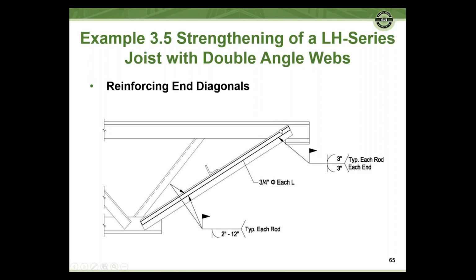Now, if you find out that you don't have 11 inches here, remember, we looked at it as 3/16. We found out this web member was a quarter. We could always increase the weld size to a quarter, or we could add weld along the inside edge at the toe of the top chord or bottom chord to get the weld length we need.